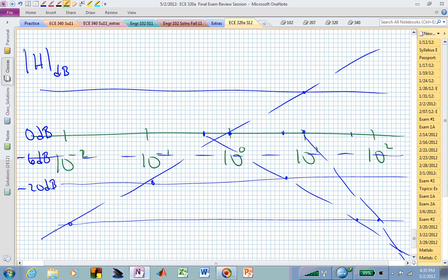Now, how do we do this? Now, this guy is sloping all the time, but we need to adjust everything by minus 6 dB. So if you looked at this as being minus 40, we really need to go down to minus 46 dB. Nothing else is kicked on here. We're at minus 20, so this should be at minus 26 dB. And you might just label that so that you know, or that I know, that that's what's happening. And all of this will be coming up until we reach 0.5, and at that point, what happens? Now the slopes cancel, don't they? We were going up plus 20 dB. Now we're going down also minus 20 dB. We're now flat.